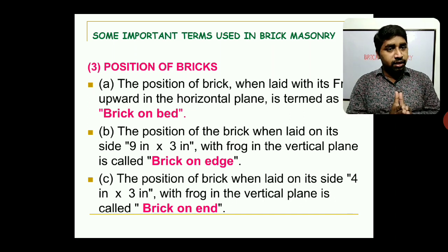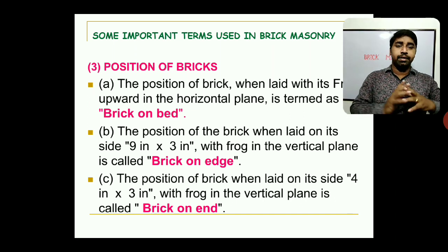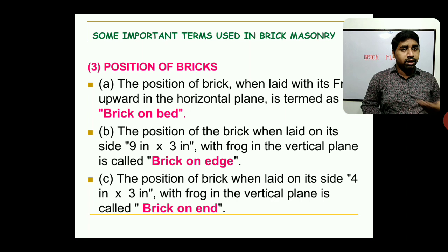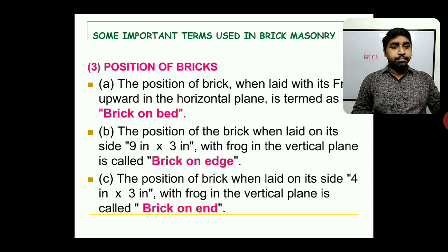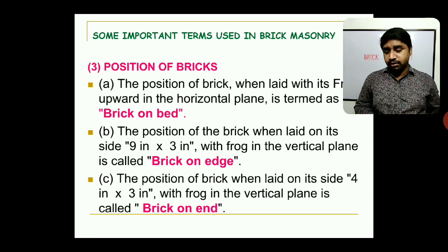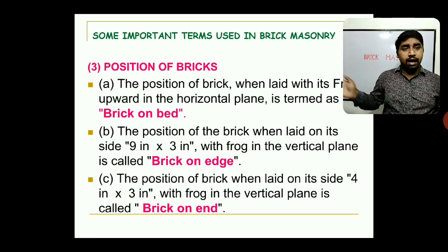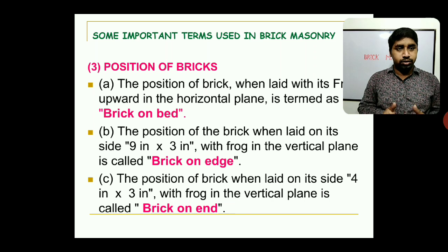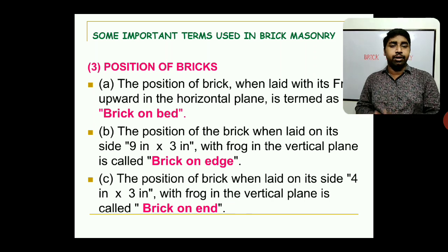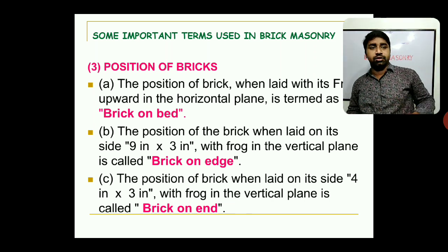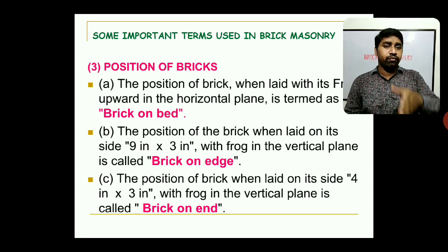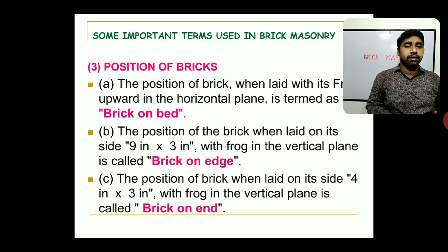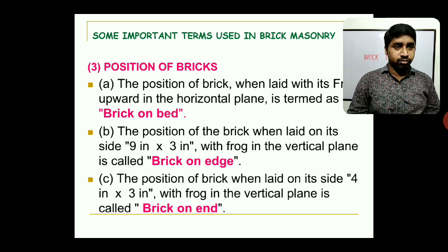When you are constructing the brickwork, the bricks may be laid as brick on bed or brick on edge. Sometimes, for example, when you are constructing almaras or cupboards, brick on end is also used. Why? Because in order to get a regular uniform projection, we'll be using this brick on end also. Okay.